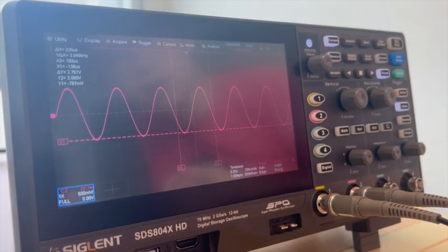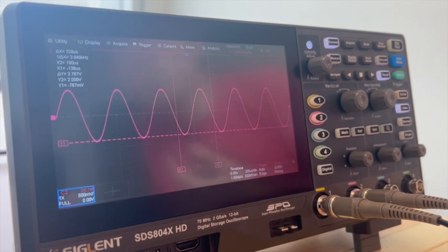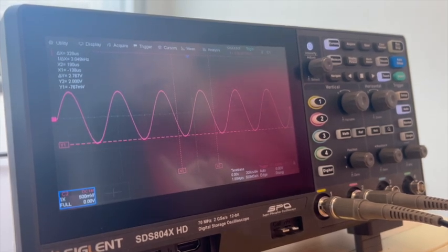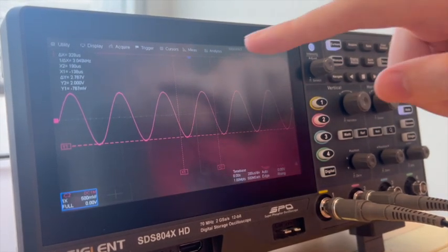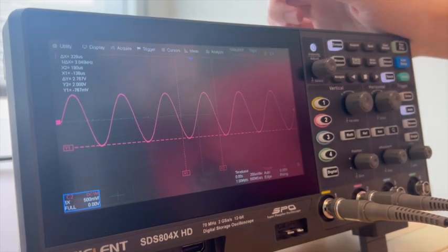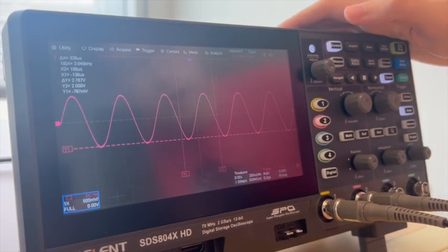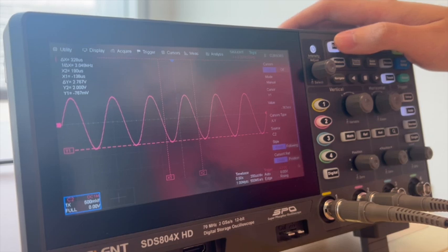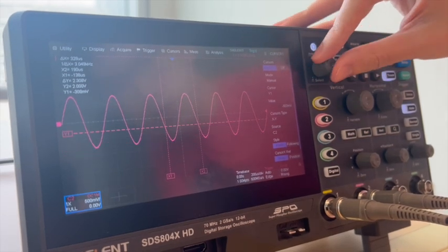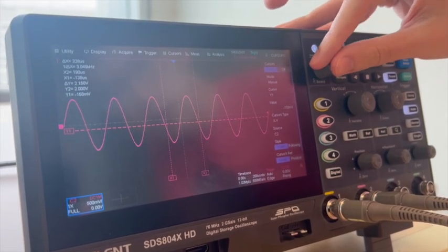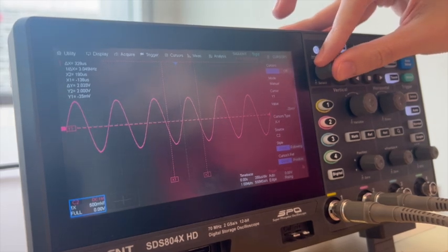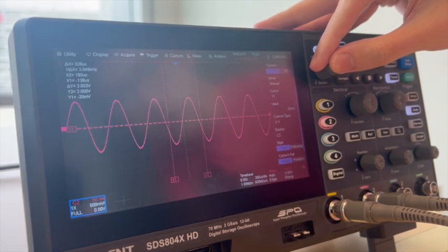And then as you'll see for your second or third circuit, there will be a DC offset, so this value will be different. But for now, let's just find our offset, or our magnitudes. So we want to take our first cursor, this guy, and then we want to put him on the middle of that line. So basically the middle of our sinusoid.